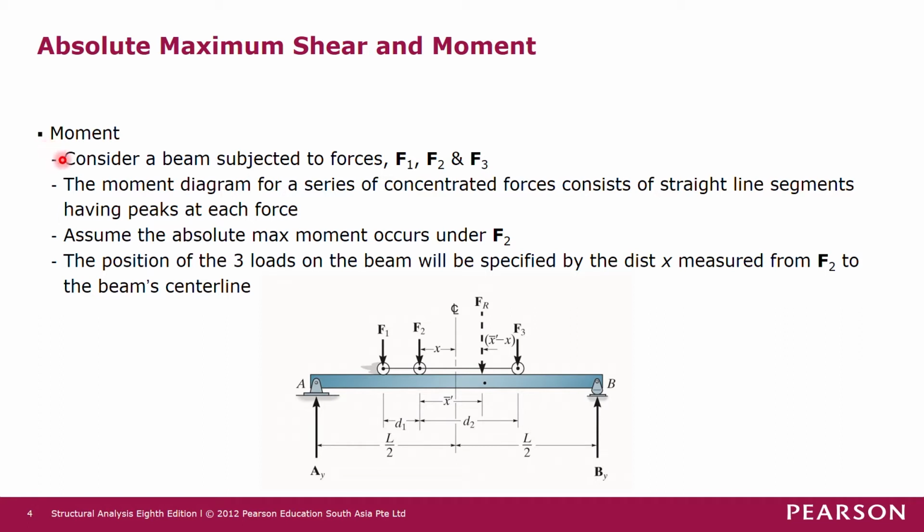Consider a beam subjected to forces F1, F2 and F3 like this on a simply supported beam. The moment diagram for a series of concentrated forces consists of straight line segments having peaks at each force. We have learned this in strength of materials already.